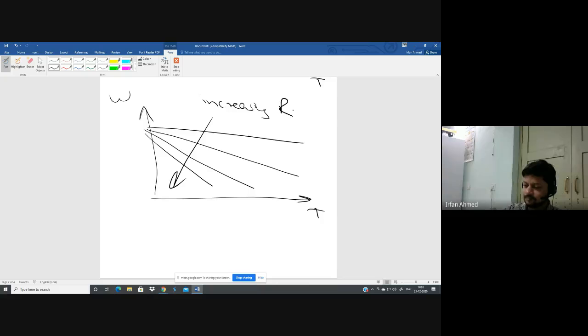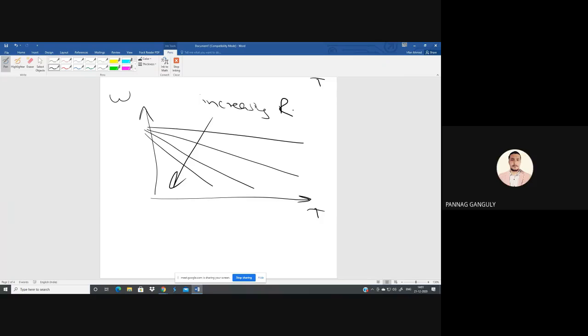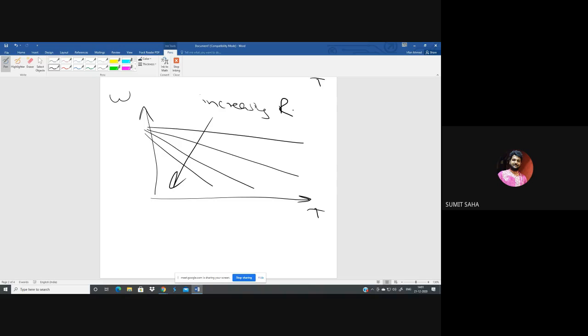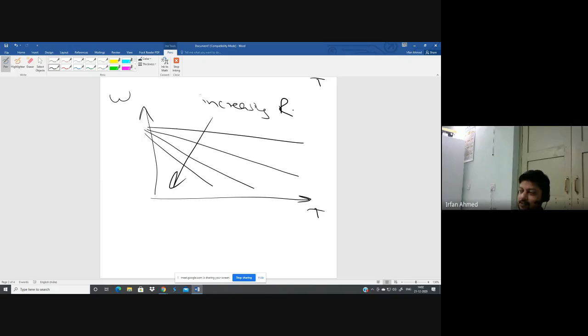Okay, everyone. What is the advantage of this method? Sir, loss. Loss is not an advantage. Only by changing the resistance we can achieve the control. Controlling is easy, it is very simple. All you have to do is connect an external resistance and change the resistance. You can change the speed. No need to study power electronics, no need for any power electronic devices, no microcontrollers, microprocessors. Nothing is required.